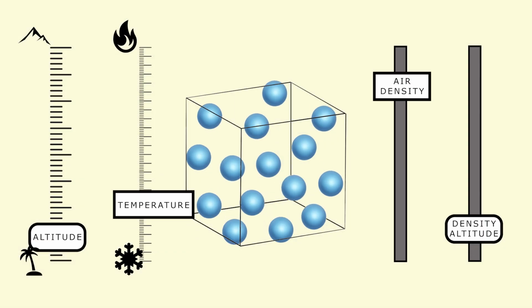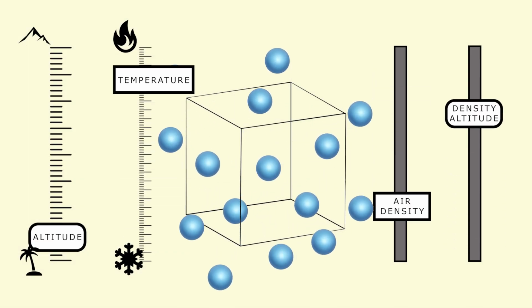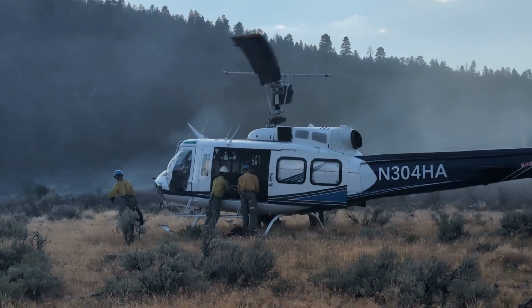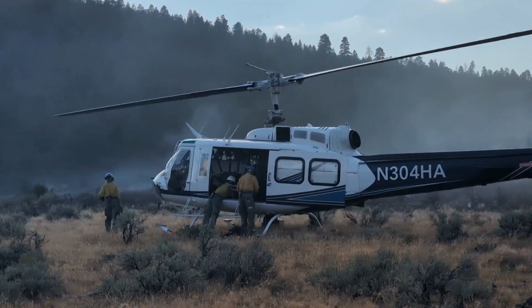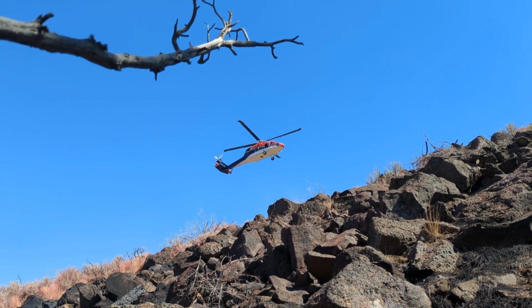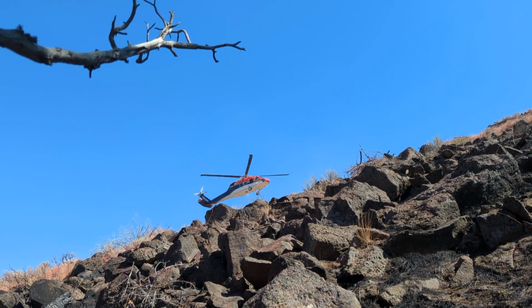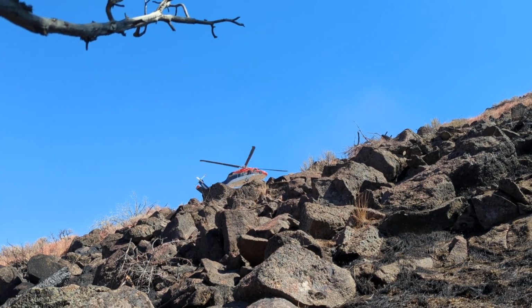During warm summer months, plan helicopter missions for early morning, when the air is cool, to maximize the performance of the helicopter. If you add hovering out of ground effect, or HOGE, to your mission, remember, when it's high, HOGE, and hot, don't expect to carry a lot.